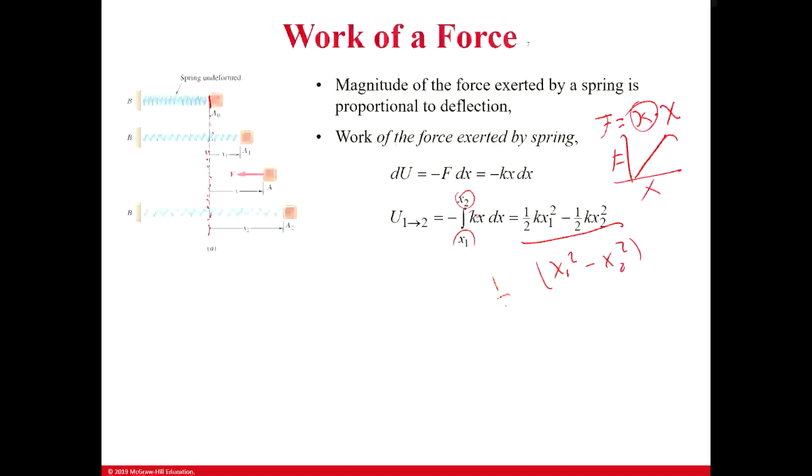You'll see this throughout physics a lot. This is an ideal spring where k is a constant, and the only thing you have to take into consideration is the distances. All right, and it's negative because in this example, it's really important that you notice this. This only applies where state 1 is a state where the spring needs energy to deform.